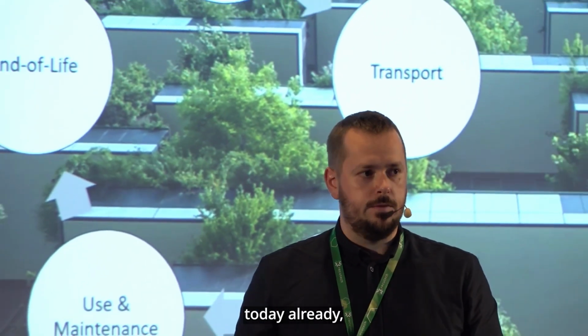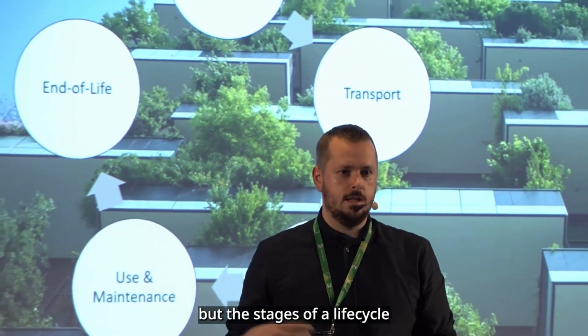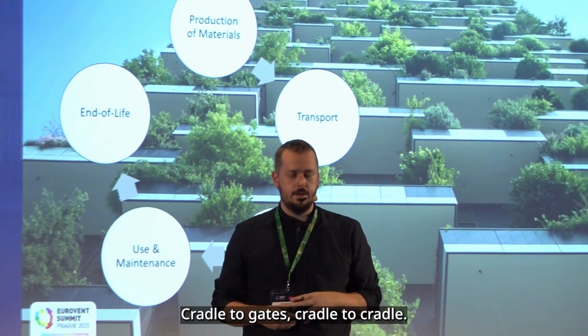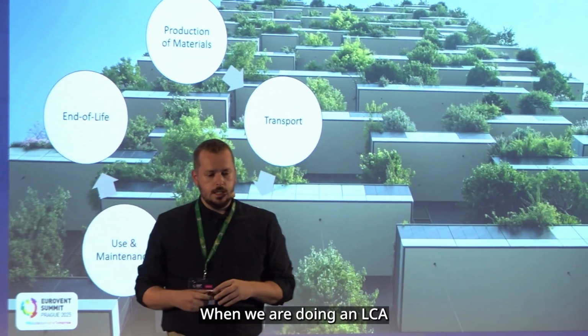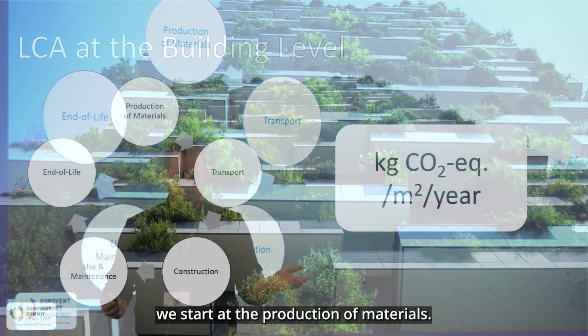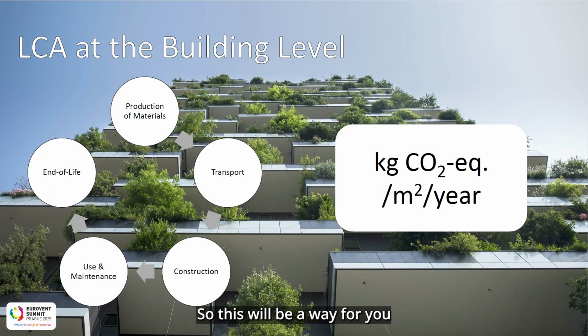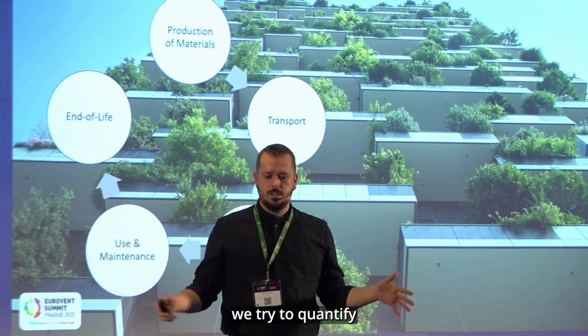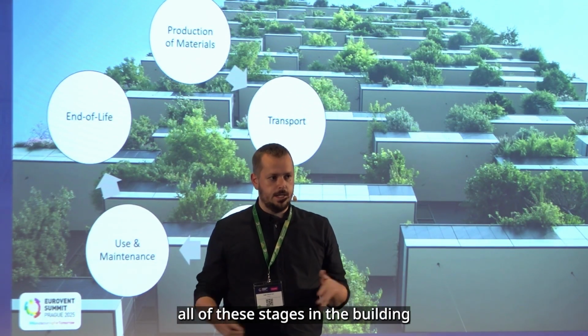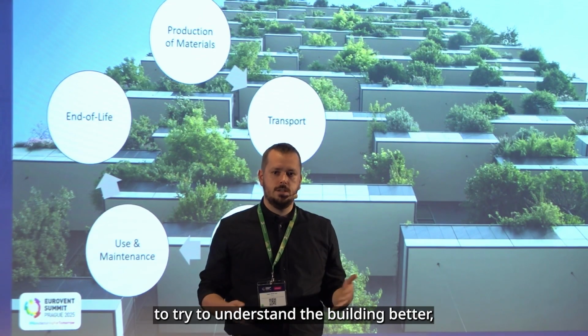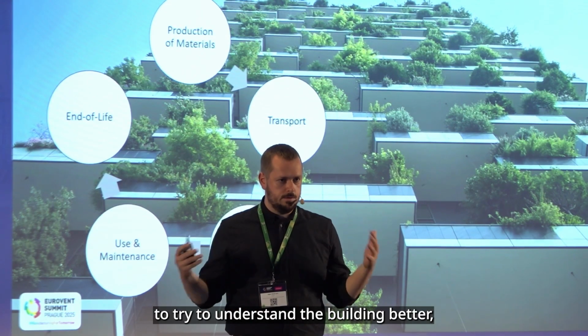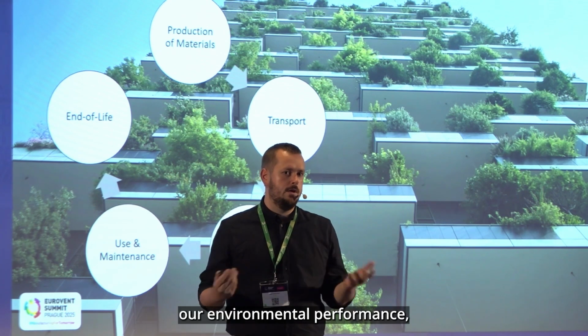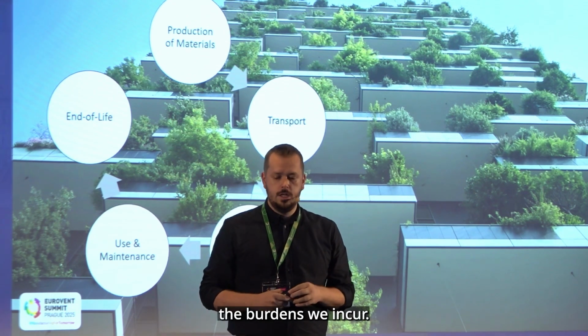We've heard a little bit about it today already, but the stages of a life cycle can go anywhere from cradle to grave, cradle to gate, cradle to cradle. When we are doing an LCA at the building level, we start at the production of materials, so this will be where you play a part as manufacturers and the data that you can supply. Transportation, construction, use and maintenance, and at the end of life. We try to quantify all of these stages in a building LCA context to try to understand the building better, using all of the data to assess our environmental performance, the burdens we incur.